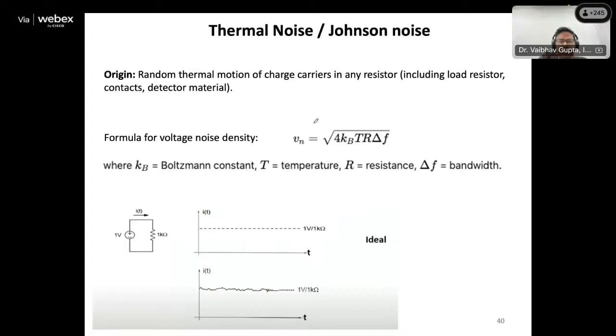Now remember that we called something like dark current. So dark current meaning when there is no photon incidenting, there is still current, and the thermal noise is the reason. So if you increase the temperature, there will be more thermal noise and there will be more dark current. But the dark current itself is a shot noise. It's not a thermal noise. The reason for having dark current is thermal noise.